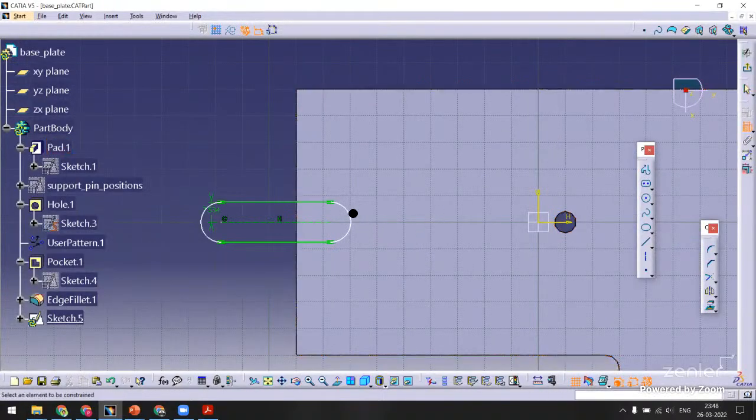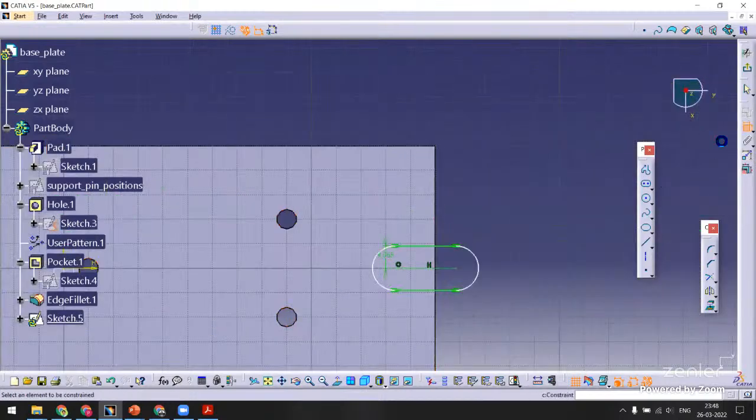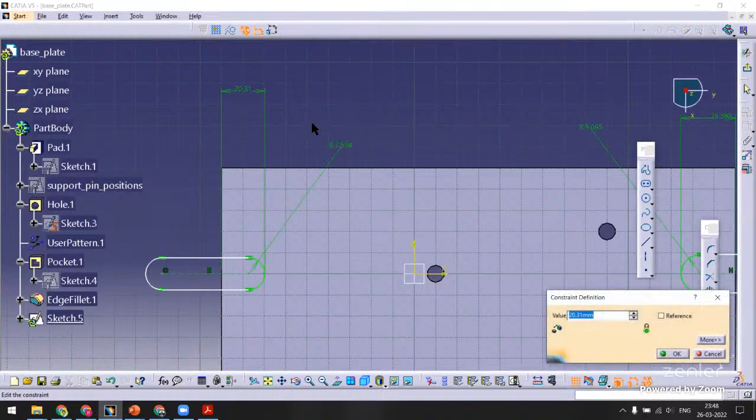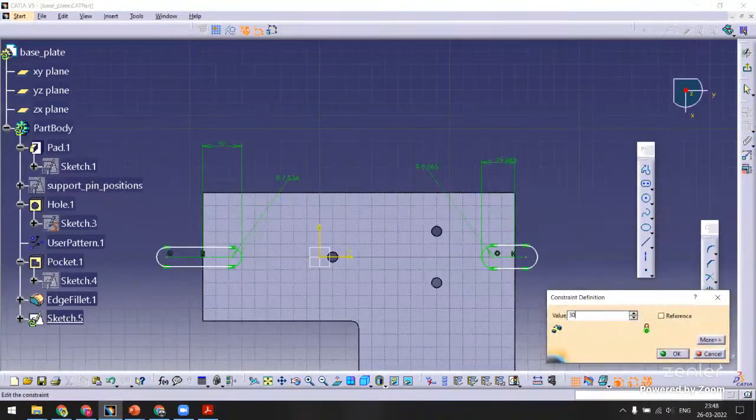Let me put dimensions for the radius dimensions. I prefer the radius dimension. Delete this. Again here, the radius dimension and delete this. Put the depth dimension. Maybe some 30 mm depth would be good for the clamping purposes.